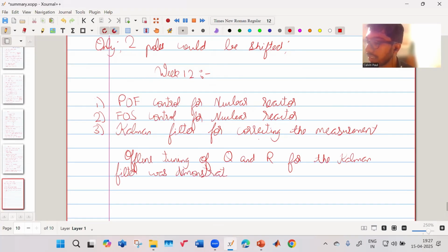So Sir selected one value of R equal to 1 and he kept on changing Q and saw how the system response is changing, whether by increasing Q it is accurately following, but also he observed that the noise is increasing. So through certain performance indices, you can select different values of Q and R and train your Kalman filter on the measured data of your plant. Then after tuning your Kalman filter, you can put it online in the actual plant controller. Okay, you can actually implement it.